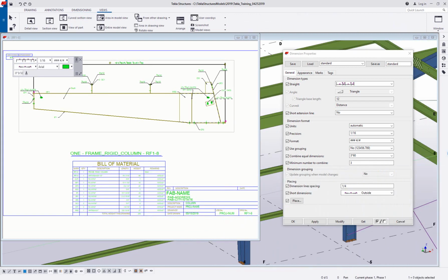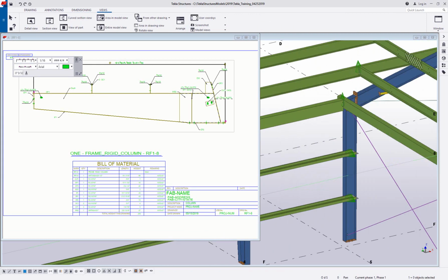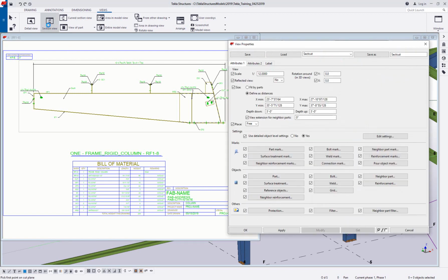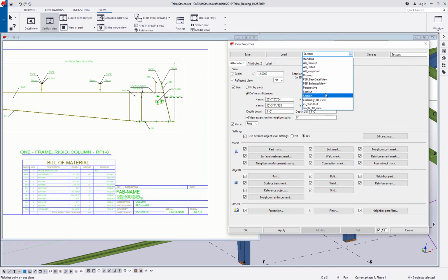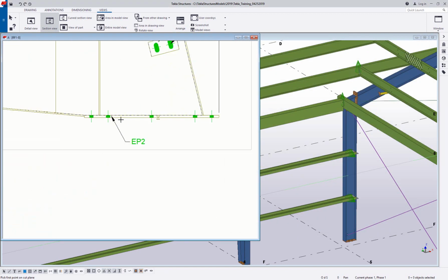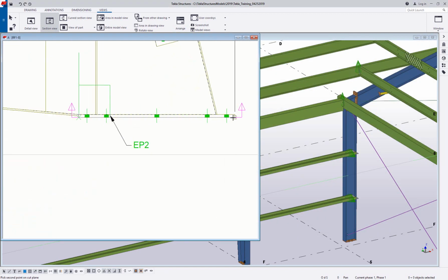Things like section cuts can also be enabled in the drawing settings to show up automatically, but you may find that with some drawing types, Tekla almost creates too many sections, or perhaps creates them in a location that you don't want to see them. So sometimes I prefer to go ahead and just create my own. And just like we showed you on the plan drawings, you can activate a section cut property. In this case, I'm going to use sect cut.